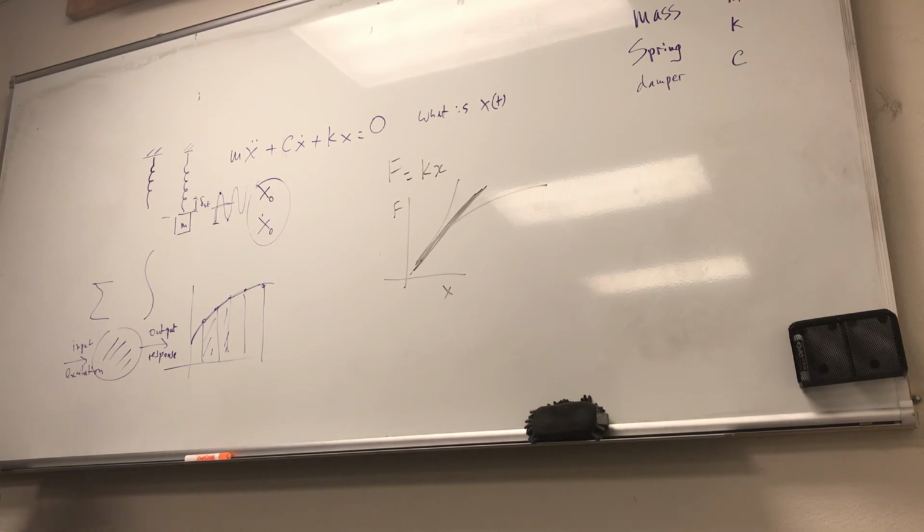I keep the anvil on its own and then model this elastic pad by putting in another spring and another damper in there, which is attached to the foundation block. The foundation block is on its own, which in turn is attached to the ground. You see how you refine a first cut model into a refined model. But how many degrees of freedom do we have here? 2. So this is more complex to solve, but it is more representative of the actual one.